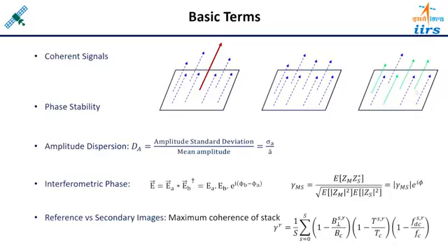In this particular resolution cell, two types of targets are there. One is blue, and another type of target responds with backscatter energy shown by the green color. So two types of scatterers are there, but both categories respond more or less in a similar manner. So again the coherence is not very high, it is of moderate scale. So these types of resolution cells are again called a distributed scatterer. Here I have mentioned two types of scatterers: one is the persistent scatterer, another is a category of the distributed scatterers.